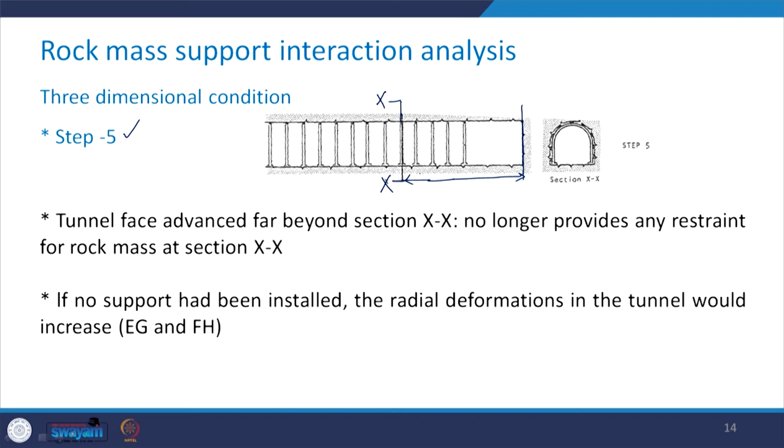So this tunnel face, which is advanced far beyond the section XX, no longer provides any restraint for the rock mass at the section XX. Whatever restraint was there because of the presence of the tunnel face is no more available at the section XX, because this tunnel face is much farther from the section XX.